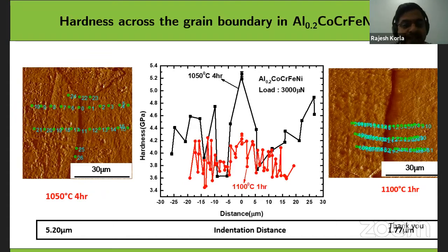This is the indirect way of saying that there is a dissolution of the elements, second impurities, from the grain boundary into the matrix, and then these impurities can precipitate along the stacking fault planes and reduce the stacking fault energy. This is a way of indirectly finding out the stacking fault energy, what the grain boundary chemistry is, what is happening, and how the grain boundary hardness structure is changing and evolving during annealing and other deformation processes.